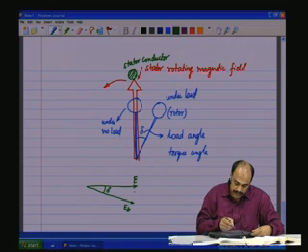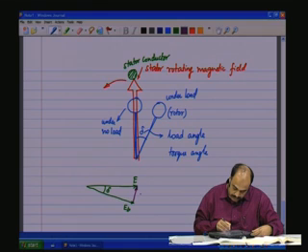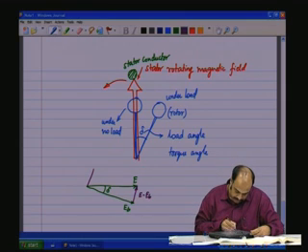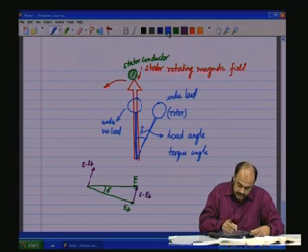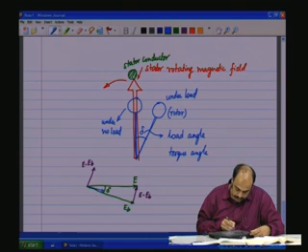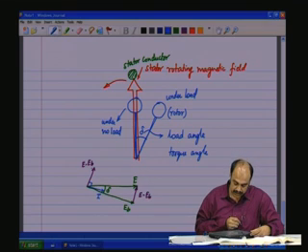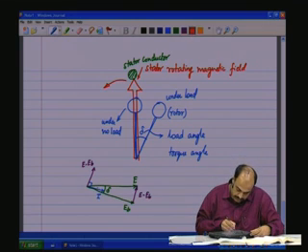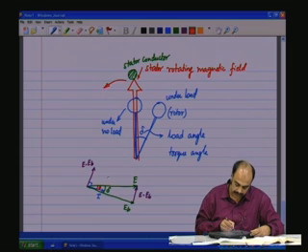Now, what is this? This is E minus EB. This is the voltage across the synchronous reactance, and I am writing it parallel here. This is E minus EB, and the current is going to be directly orthogonal to it, so this is I, which is 90 degrees lagging E minus EB, and theta is going to be the power factor angle, PF, or the power factor angle theta.